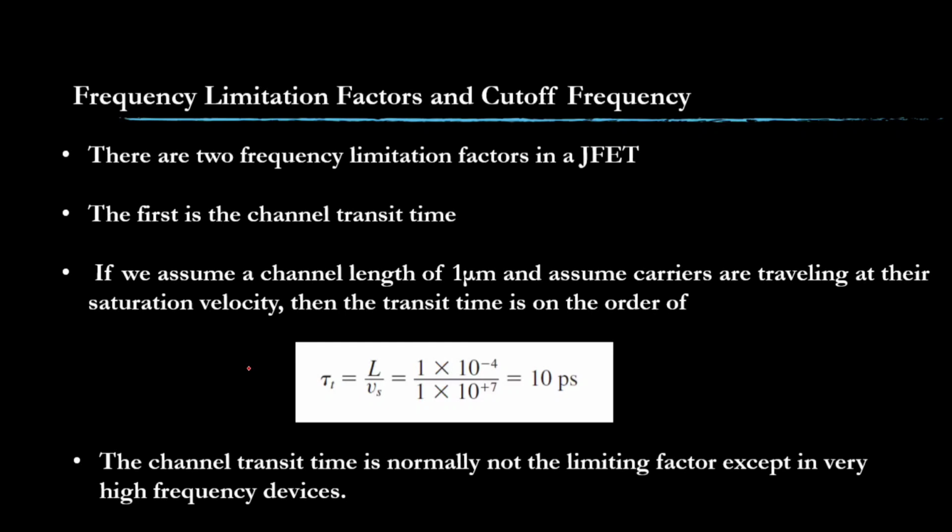And I increased it. Now the frequency is 1 kilohertz. Yeah, it's working fine. I'm getting a proper amplification. I increased the frequency to 2 kilohertz. Still it is working fine, and the output has improved. I'm getting more amplification. Then I increased the input frequency to 3 kilohertz. Just assume at 1 kilohertz I applied 100 millivolt to amplify, and I got almost 0.9 volt.